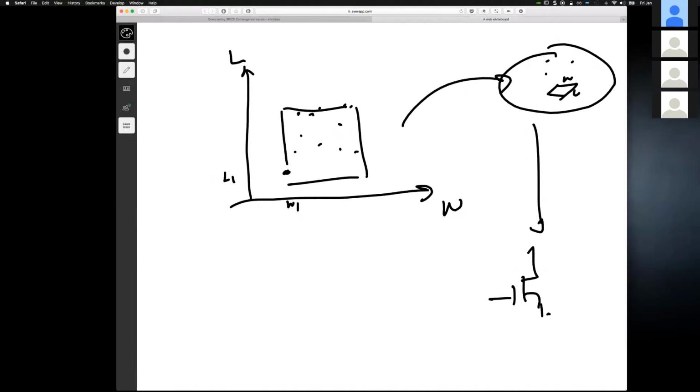Now, you can see that in most of the foundry technologies, they have the effect of binning. So they would actually say, this one is bin 1, and if you exceed a certain W or L, you go to a different area, and they characterize it differently. Now, the problem that happens is that when you're fitting the models, depending on which process and which effect, there probably won't be one that fits all.